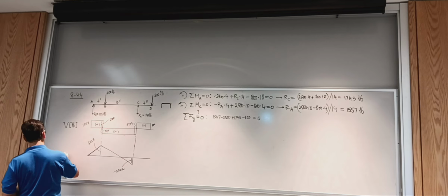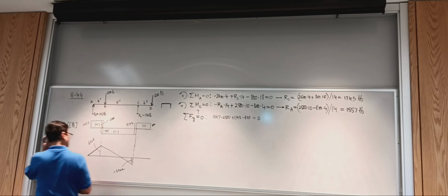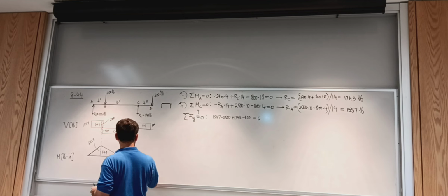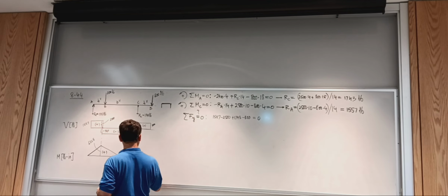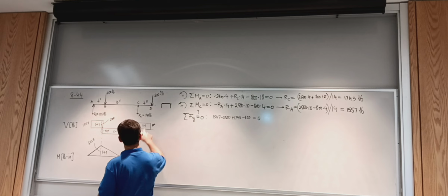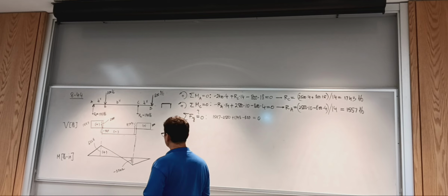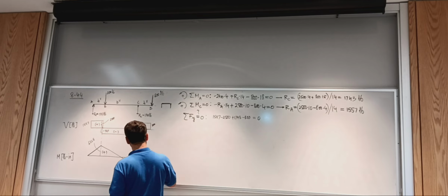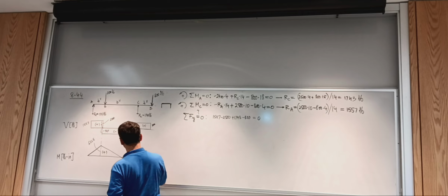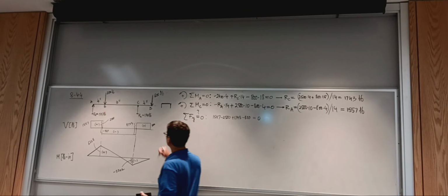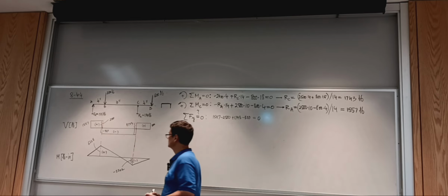Again, we're working on moments, and moments will be in pound inch. Okay, so this is positive. We went negative. This should close to 0. I still have this. So if I'm adding 800 times 4, I need to get negative 2 because of rounding. Okay. So yeah, diagram close to 0.